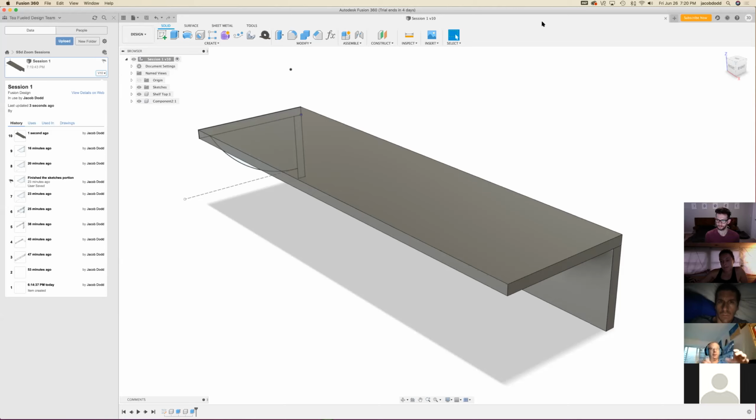Then every other board just slides on top of that, and you make sure that the end is correct, clamp it down, and then cut. Now every board is cut in reference to that one. Yeah. In the same way here, by referencing the end face, you're referencing where everything else should come to.